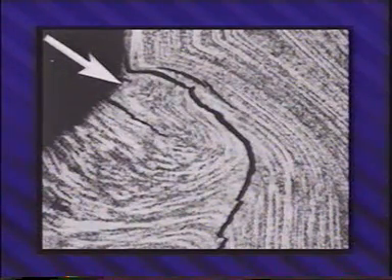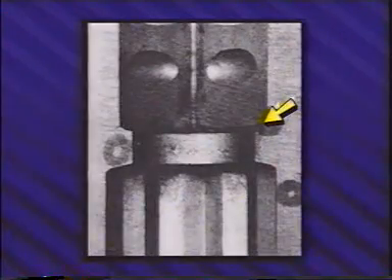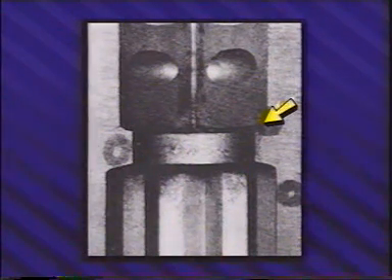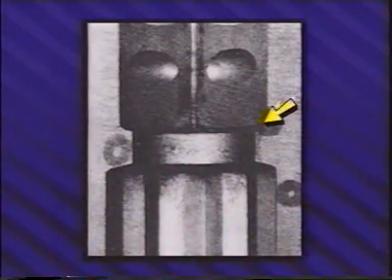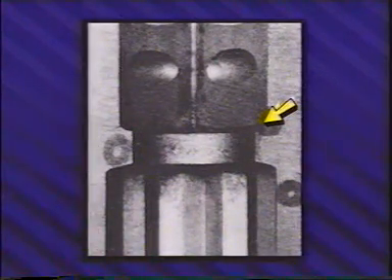The movement of metal during these processes makes them susceptible to the formation of surface discontinuities. Laps, seams, and cold shuts can form. Oxides, slivers of the base material, or foreign material can be embedded into the surface. These surface imperfections produce notches of unknown severity that act as stress risers under load. They may also serve as sites for crack initiation during fabrication or in service.